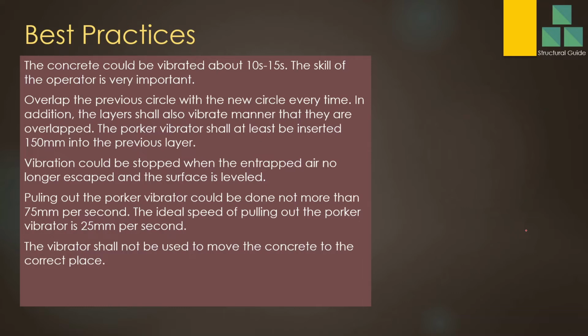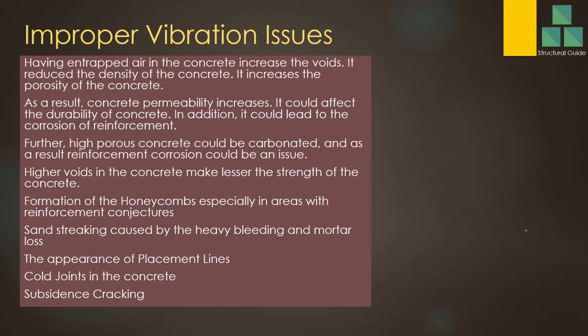The vibrator shall not be used to move the concrete from one location to another. This is a very incorrect method. We have seen some people during construction use the poker vibrator to move the concrete. That is not best practice. There will be issues like segregation and other issues.